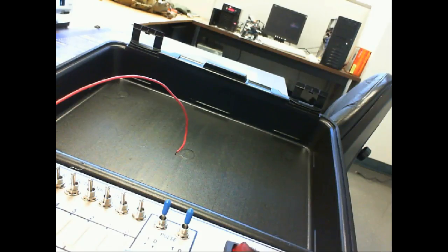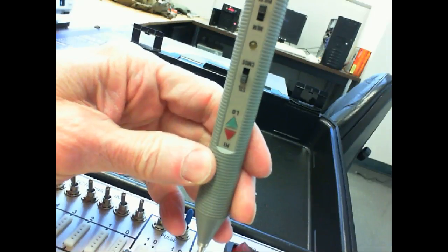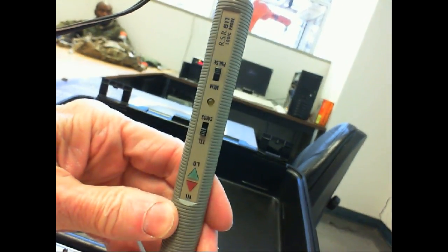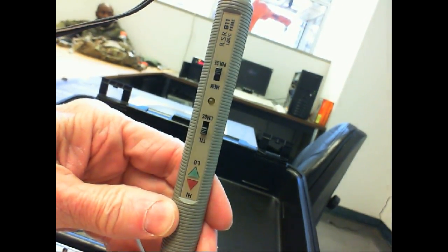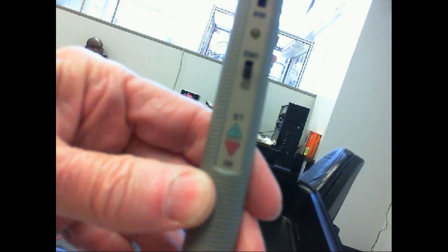Let's see what our logic probe tells us. So this guy here is on. Both these are what? So this is the big difference. Right now, if I measure this, it would measure over 2.4 volts. Right now it's illegal. So if I put it in there and neither lights are on, it means that's an illegal level. This guy right here is still lit up, right?